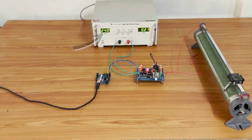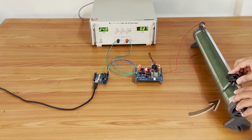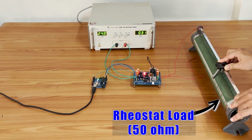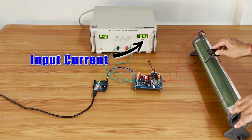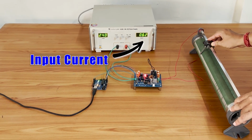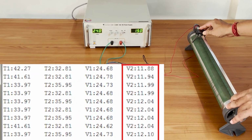In the new experimental setup, the input voltage is set to 24 volts. A 50 ohm rheostat is used as load. So we start by increasing the rheostat load. You can see that the input current increases gradually. But the output voltage is constant at 12 volts.